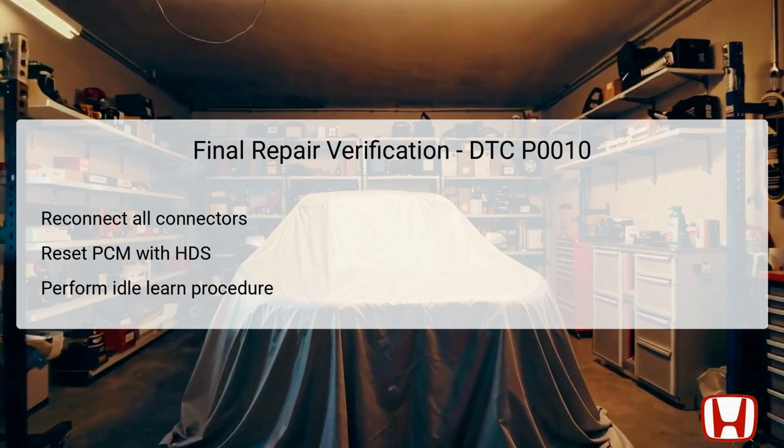Finally, execute the VTC test within the HDS's inspection menu to ensure no faults persist. Monitoring the OBD status for DTC P0010 is essential. A result indicating passed will verify that the issue has been successfully resolved.